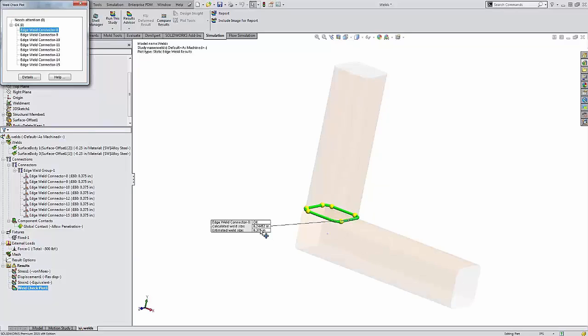So we had 0.375 on all of our beads, but this one in the front could have been smaller. Could have been 0.24. Around the corner, that one is pretty close. It needs to be 0.345. On that side, 0.281. On that fillet, 0.29. This back one, 0.07, so it doesn't carry really any load at all.